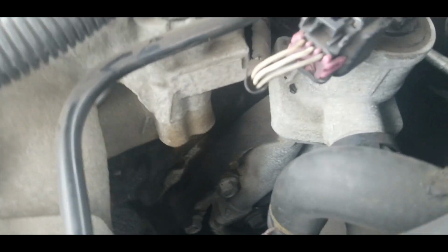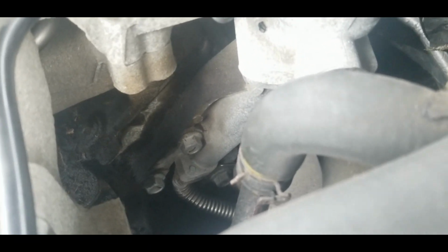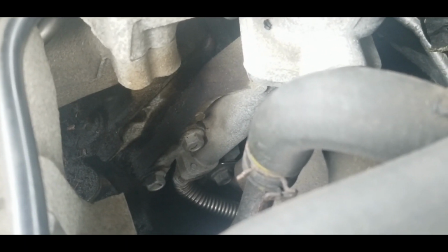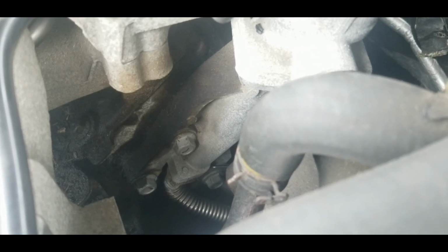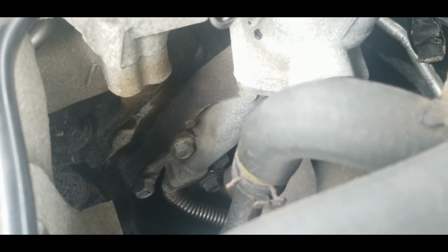When it goes into the cylinder head, there are channels where the air flows through the cylinder head directly into the exhaust manifold. So when the pump is on, the air flows directly into the exhaust system, into the manifold, and goes into the catalytic converter.